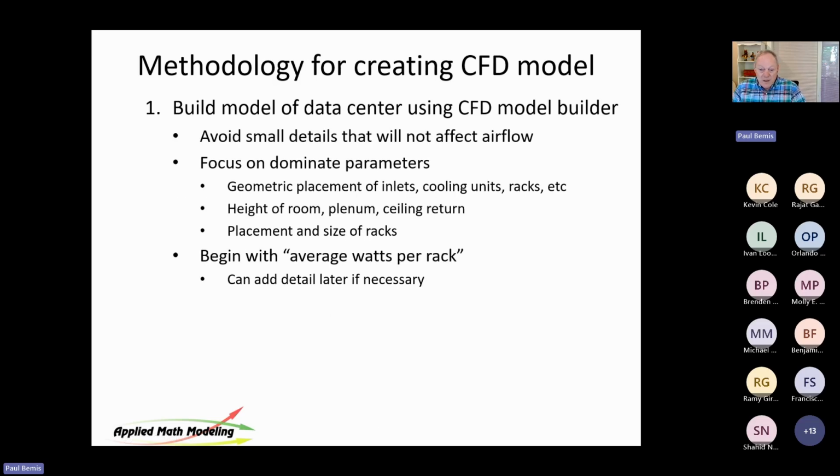So I'm pointing that out to you because I'm going to bring it up as we go through the results. I'm going to talk to you about the trade-off between dynamic and static. Makes a big difference in the data center design. Unfortunately, the air comes out of these big pieces of equipment called air handlers and floor tiles and things, and as a result, it comes with velocity. And that velocity is not your friend. It tends to reduce static pressure.